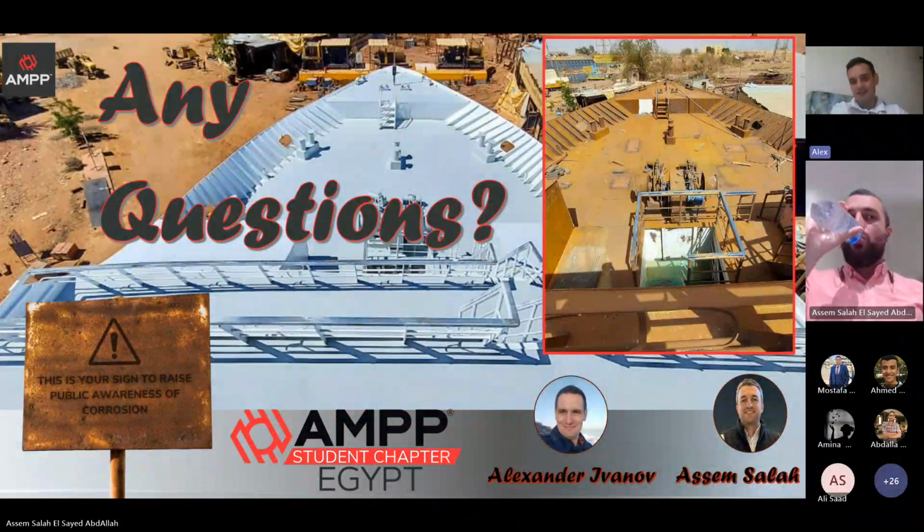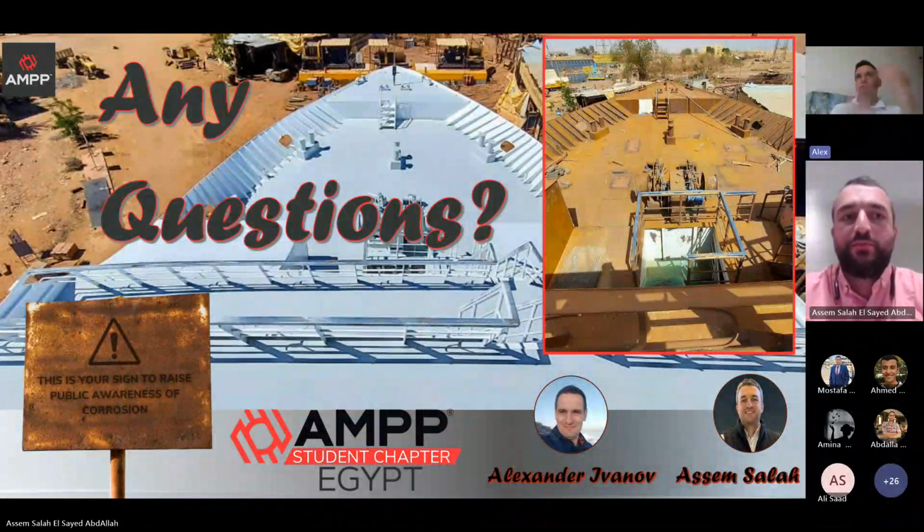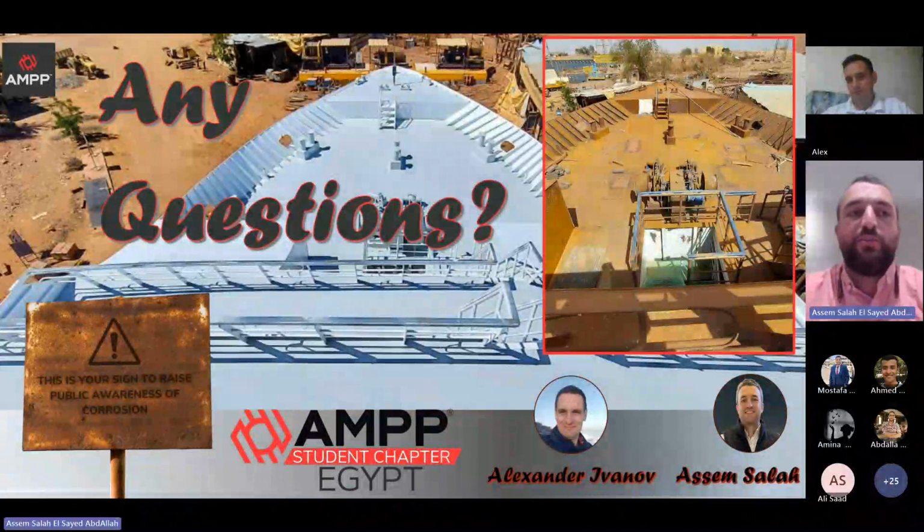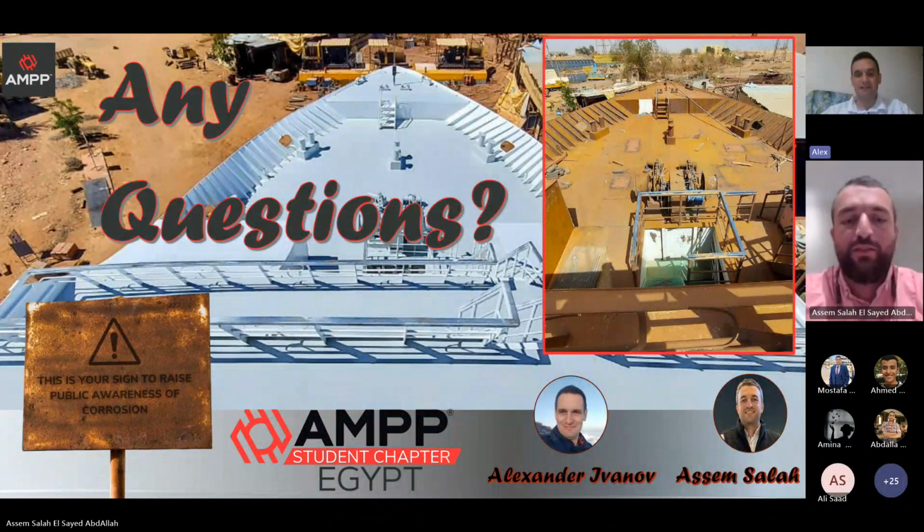Yes, sure. This aluminum oxide acts like self-protection, but in the marine sphere we very often paint the aluminum parts of a vessel. We don't do anything with aluminum, just clean it from the dust and then apply special primers that are suitable for aluminum, and that's all. For example, you want everything in one color, like corporation colors. You may apply coating for the aluminum, but only for the appearance, if you want to give color, not for protection. Yes, it protects itself with aluminum oxide. But yes, you paint it just from an aesthetic point of view.